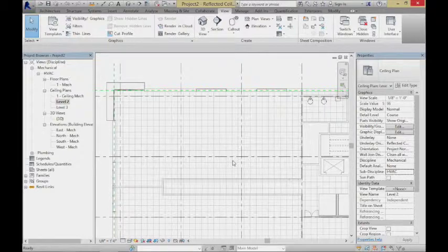Let's think about this thing. So as we're laying this thing out, I tend to start by actually putting in diffusers or terminals. I'll put in supplies and returns just as endpoints for me to work with. So let's see what we got available. Okay, I'm going to put some things on the ceiling. Some of the default ones that loaded are like little 2x2 ones, so they fit nicely into this kind of ceiling grid. Okay, each of them is going to have a certain capacity associated with it.